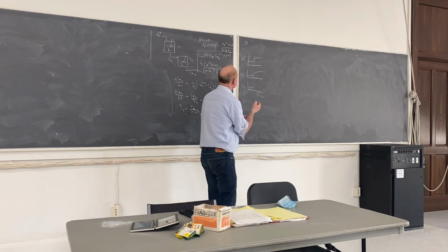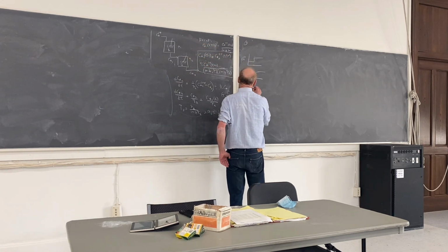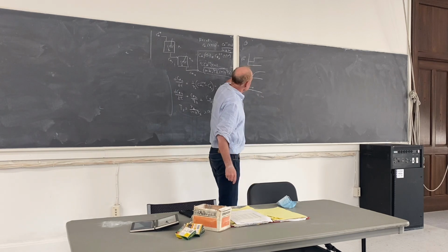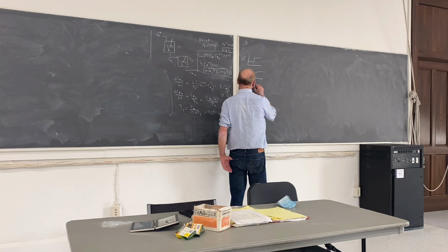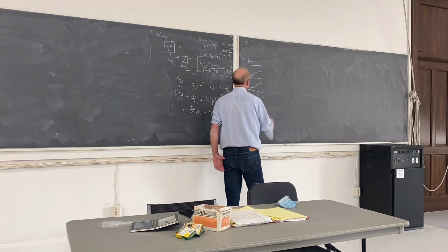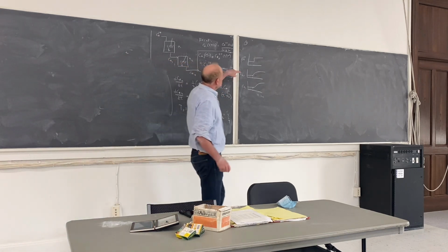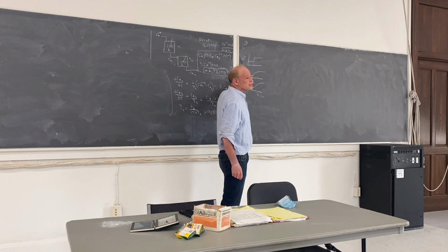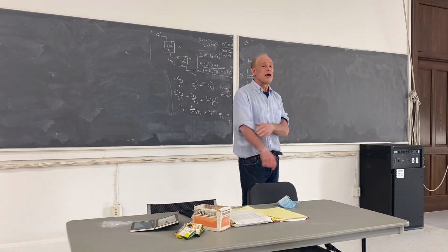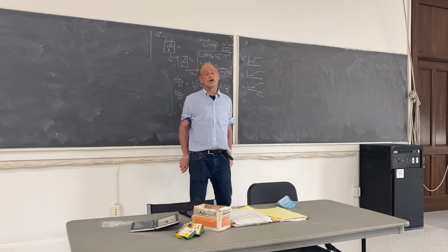Again, the assumption was for t less than 0, they were all at steady state. And here we saw that instead of having a break in the first derivative, in the slope, we had a break in the second derivative. So the curve looked something like this. What I mentioned was, CA in undergoes a step change. Here, CA1 doesn't undergo a step change, but the derivative of C with respect to t undergoes a step change. And here, the second derivative undergoes a step change.